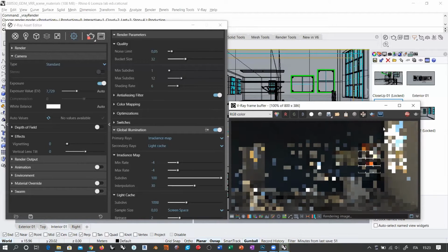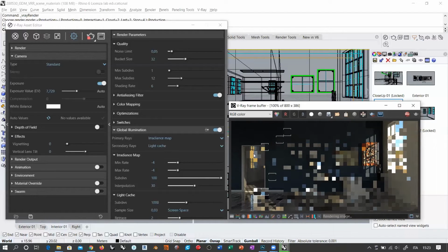Now it's going to be interesting to take a look at the final result that we are getting, because hypothetically speaking, we are considering a very low quality for the irradiance map, as we discussed in the previous session. And of course, if you use these settings in a totally white environment, any artifacts or problems that you might get with this poor light calculation quality become extremely evident.